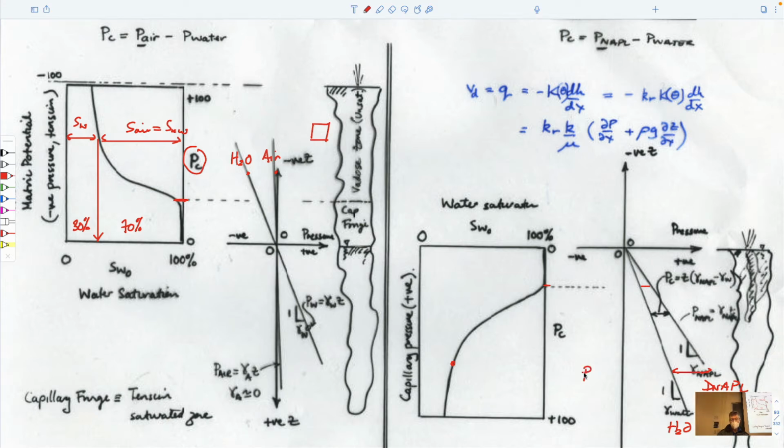So capillary pressure would be equal to the elevation multiplied by the density of the non-wetting minus the density of the wetting times gravity. These are unit weights. That's all this is. And again, it just defines a behavior so that as you go further within the subsurface, if we're at a depth corresponding to a capillary pressure of whatever, then the saturations in this particular case would be,